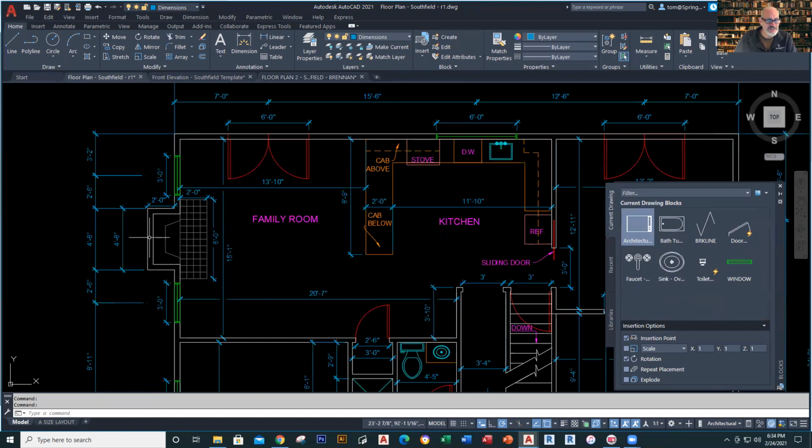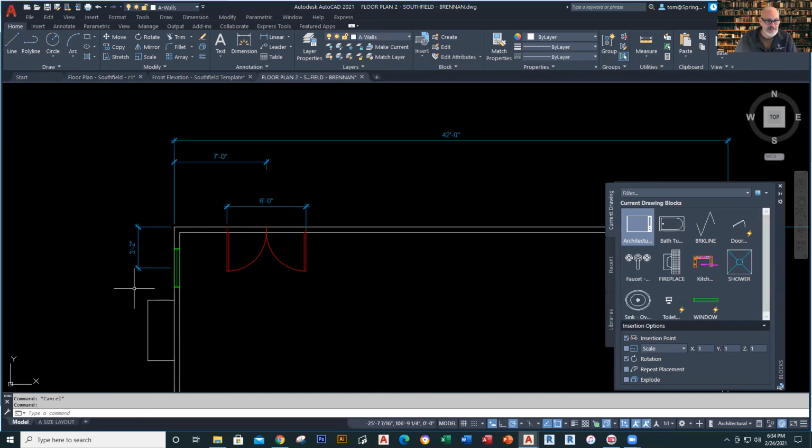Now, what is the size of that? Well, that's also going to be a 5-inch offset right there. So I'm going to go ahead and offset those as well. So back over to here, I could just join these together, make life easy. Type in J, then offset it 5 inches, and I'll go here like that. And then what I could do is simply trim this out right here, right there.